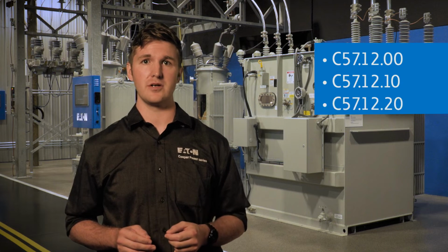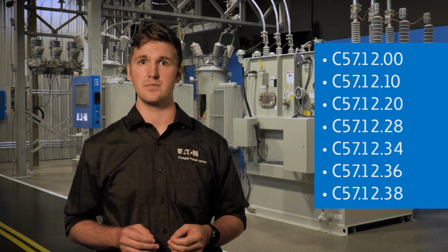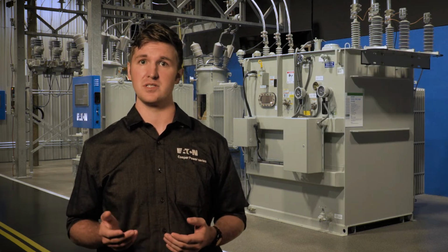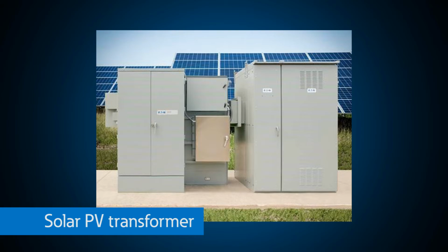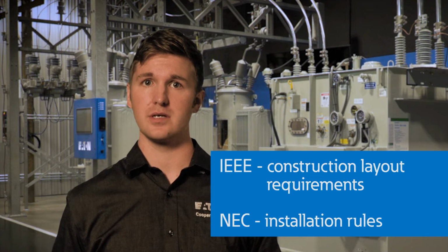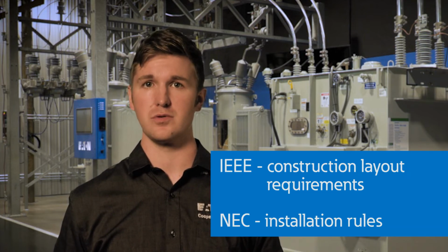These are the primary standards used for liquid-filled and dry-type medium voltage distribution transformers. There are many other standards that may be applicable to more specific applications such as solar PV systems or network vault type applications. While IEEE dictates the construction layout requirements, it is the National Electrical Code, or NEC, that is responsible for installation rules.